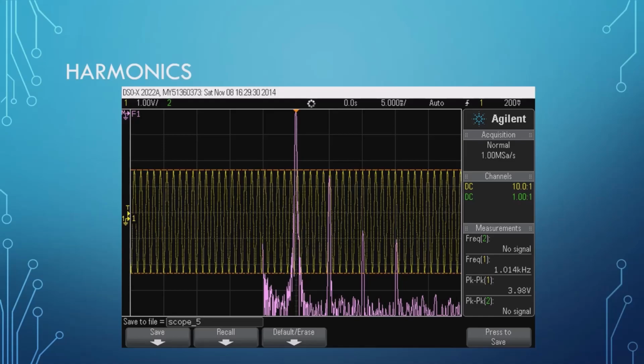We want to degrade those so that they do not interfere with the other bands. I think some of us saw that when we were playing around with the 5351 on Saturday during the build, and I brought up the full sweep of the spectrum analyzer. You could see your signal at the max, and then a bunch of other signals, and those were the harmonics being generated. So we want to clean those up.